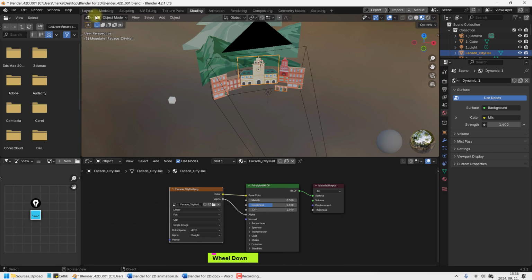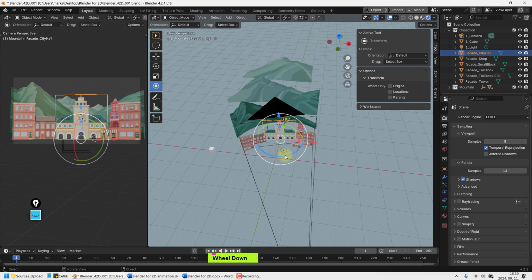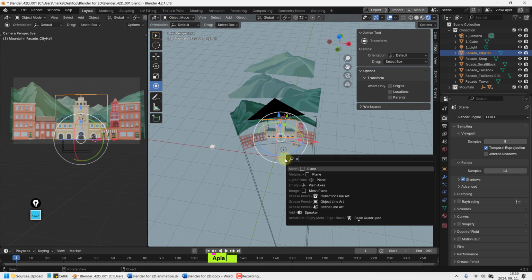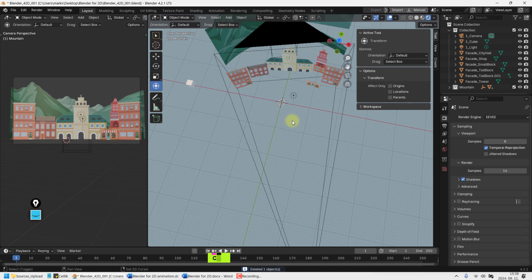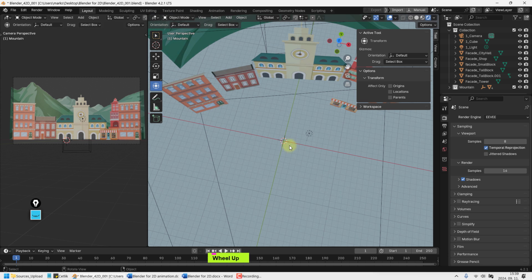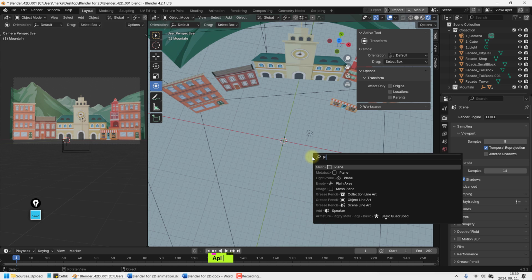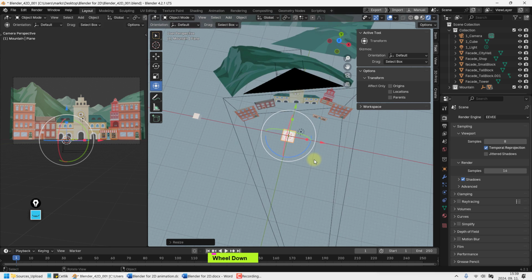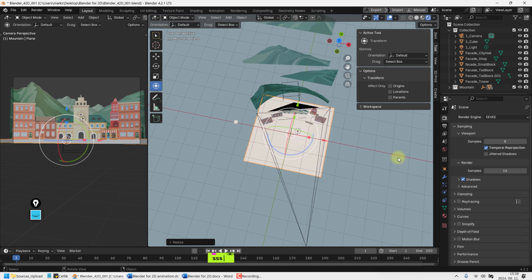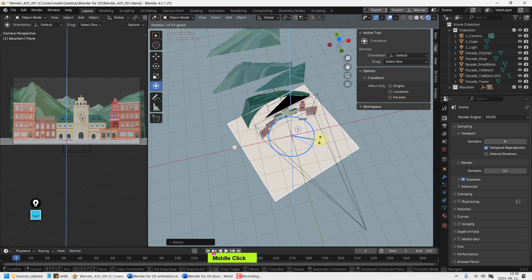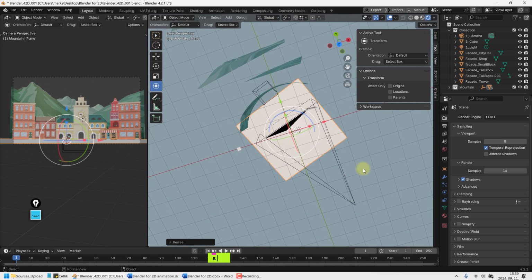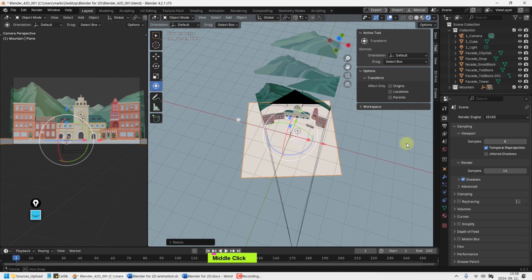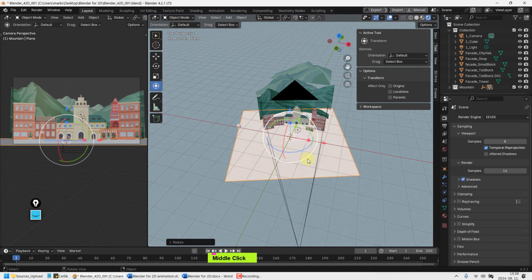So we can go out and create a ground, Shift A, and plane. And because this was here, I will delete this. Press Shift C. It will reset the origin, the cursor point, and Shift A and plane. So now I don't have to worry about this, and just scale it up and rotate it around. And maybe don't need that much of a scale, but it's good. It's just a single polygon anyways. It's not a crazy thing.